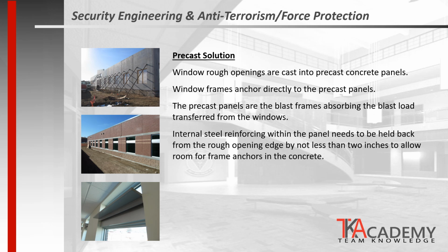When concrete or precast walls are being used, the internal steel reinforcement within the wall panel needs to be held back from the rough opening face by not less than 2 inches to allow adequate room for the frame anchors to embed into the concrete.